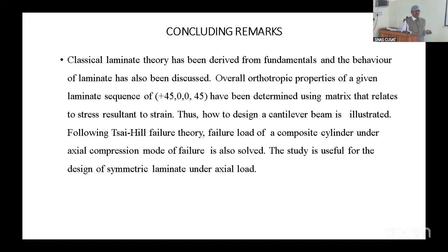Here, I have not explicitly told that the layup sequence has to be symmetric. You see, a leaf, when it is dried in the hot sun, what will happen? It bends. The leaf does not elongate and dry as it is. It will have twisting and all that.